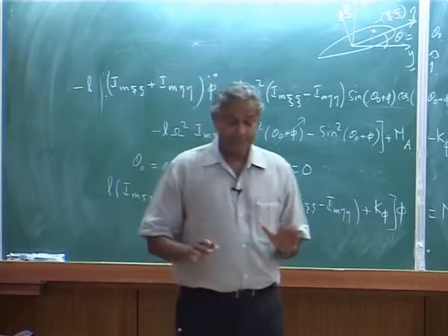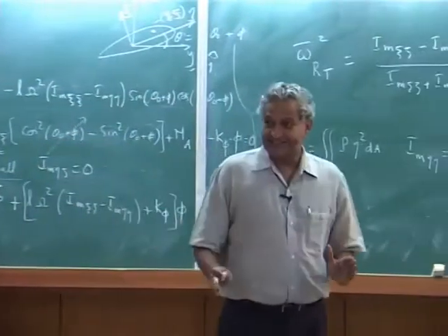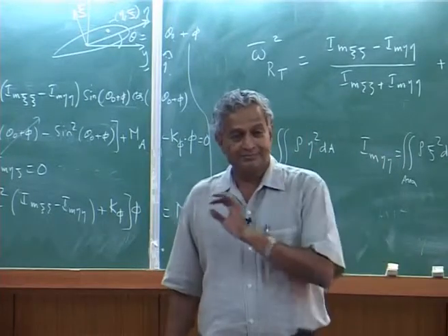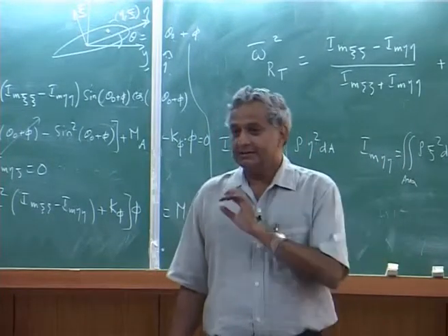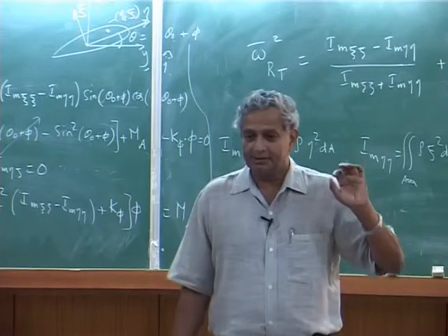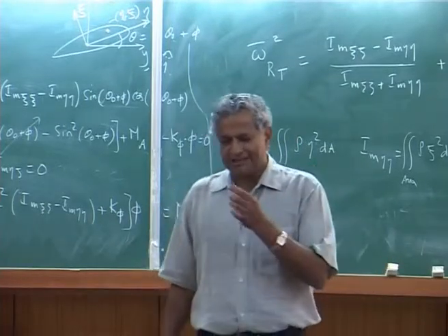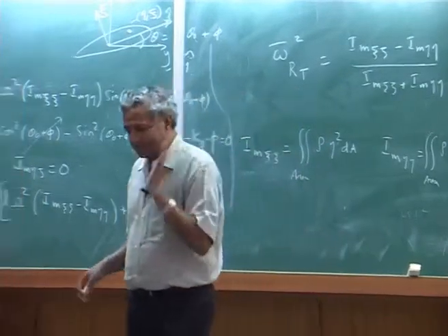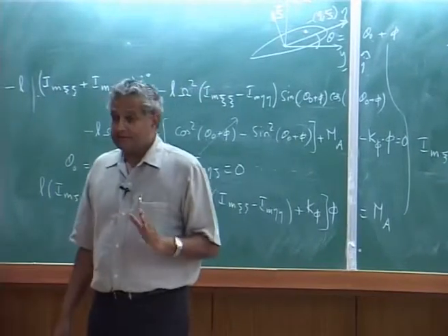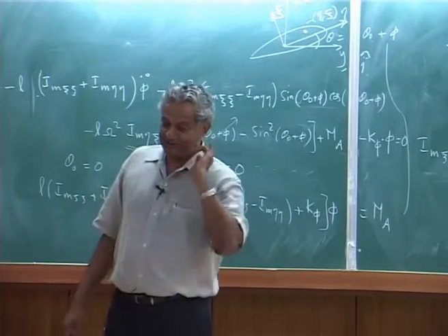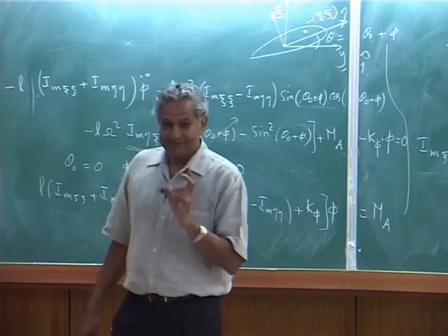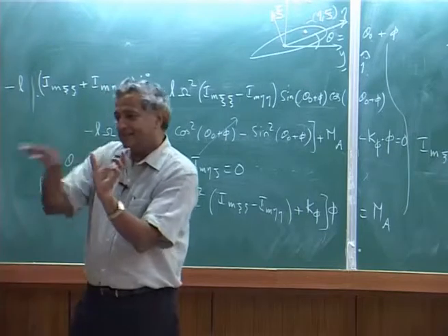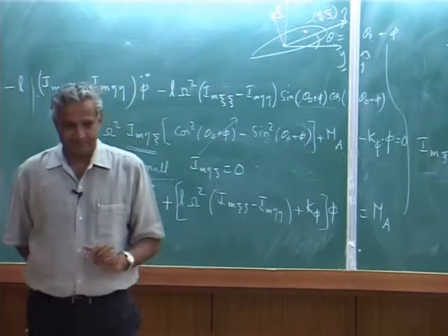So, here the blade is designed such that the mass center is at 25% chord, elastic axis at 25%, but exactly 25, no, if it comes to 24.589, it is okay, take it. Yes, the elastic axis of the cross section is also at 25%. This is where the design goes through several iterations. The box beam is kept only near the leading edge, the trailing edge does not contribute anything.